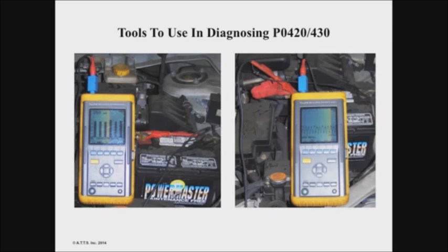Well, you can see on the right side of the screen, I coupled my lab scope to AC voltage, and you see the little humps? What I'm looking for is either a space or a higher hump, something like the odd man out. In other words, something that looks odd, correct? And that's a way to find it. You'll see a couple more examples coming up.